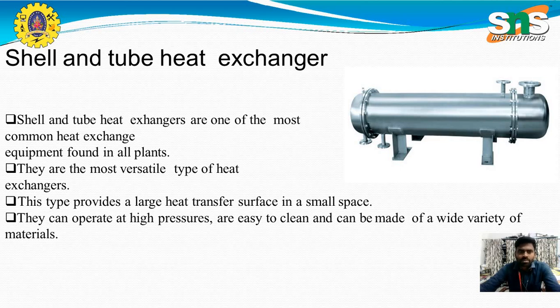Inside the shell we have n number of smaller tubes, so when you increase the number of tubes, automatically we have a larger surface area for the heat transfer.